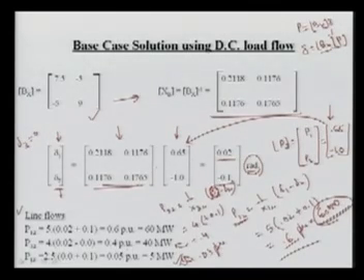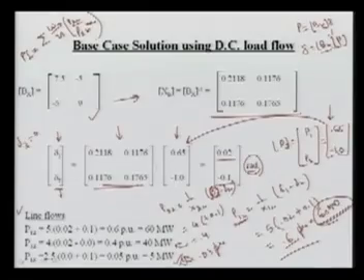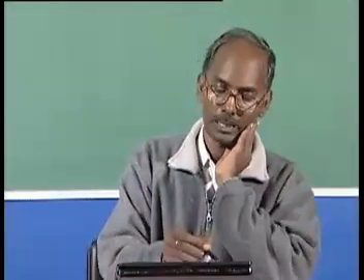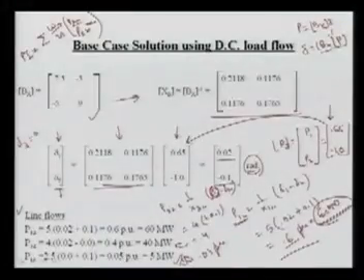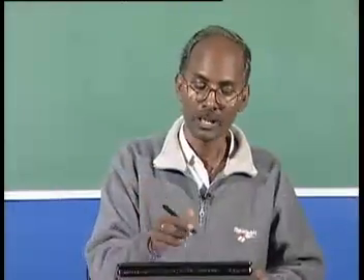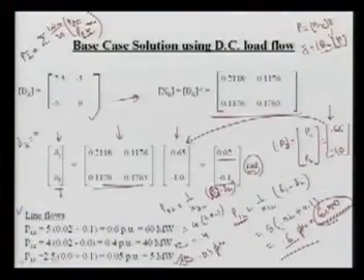Another thing I want to mention here, in this power flow definition, I use PI for line flow. It is a summation of omega m upon 2n, here PLM upon PLM maximum. You can use PLM and PLM max in per unit or in megawatt, but proper care should be taken that if you are taking the line power flow in actual values, that is megawatt or kilowatt, then you have to use the rating also in the same unit. Then there will be no change. If you are using per unit, you can use both in per unit and solve it without any problem.